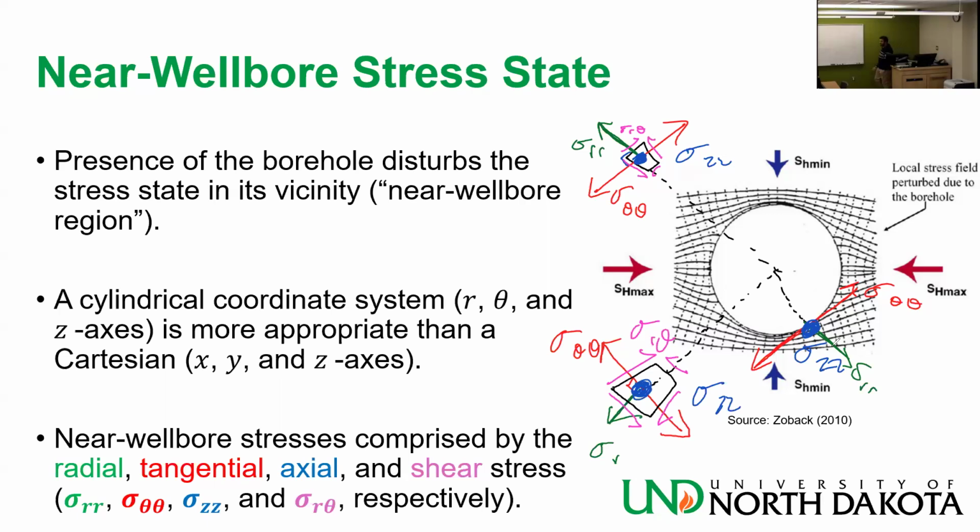And I will tell you, don't worry about the shear, because it goes to 0 on the wellbore circumference. And then you're going to tell me how so, and I will tell you to wait until we see the equations. I believe you have already seen the equations. If you see the equations, you will see that it goes to 0 at the wellbore radius. So these are the stresses when you have the wellbore presence.